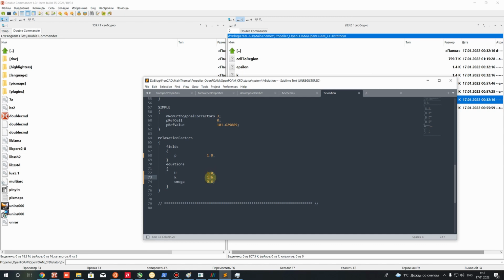But for this relaxation factor, I think you will get very high instability of simulation and maybe a crash, because your mesh is not ideal. It is a bad mesh from the point of view of a tetrahedral mesh, and we have to use some relaxation factors. It will reduce the speed of simulation if you reduce these relaxation factors, but it will increase the stability